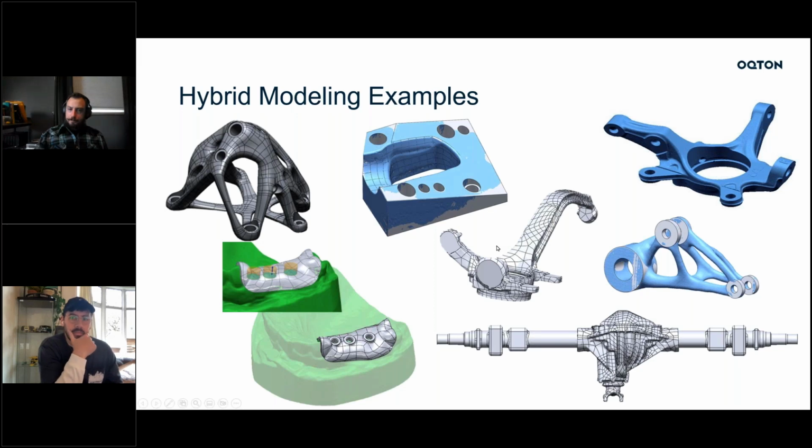We're going to be doing a lot of things where, especially some of these cast parts, you can see that there was some milling operations that happened after the rough casting or after the additive manufacturing potentially. And so what we're going to do with the selective surfacing tool is we're going to find those areas and we're going to add some stock back in, right?